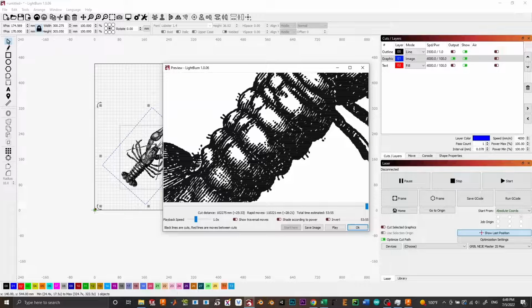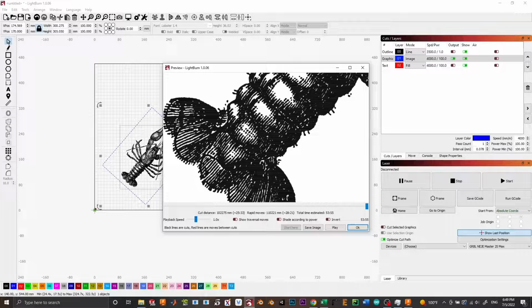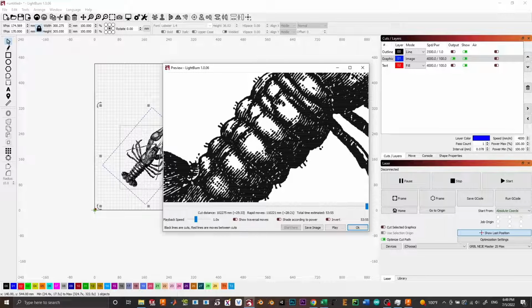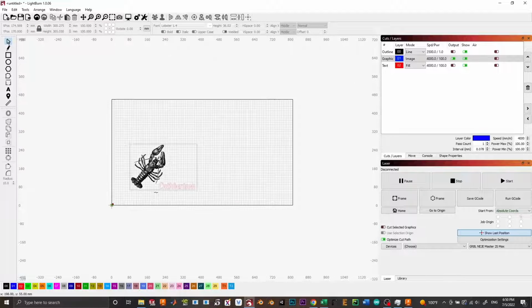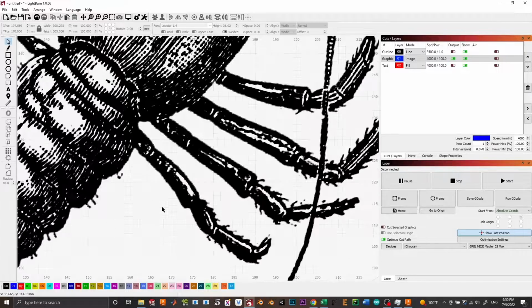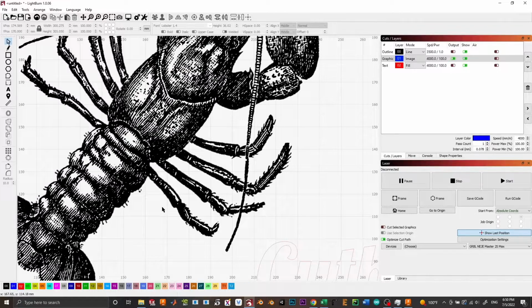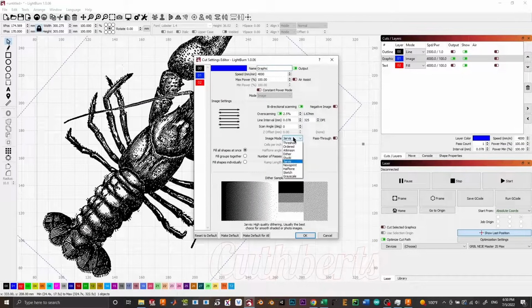One thing I do recommend, especially if you're making slate coasters, now working with slate charcuterie boards, is use some of your old scrapped coasters and just crop out a tiny section of this, about like so. Keep it scaled properly and have it engraved on a coaster just to see what exactly you're looking at, in terms of resolution, engraved time, stuff like that. It can be extremely helpful, especially for more photo-like images rather than graphics that will require dithering. Since this is just a straight black and white graphic, it doesn't require any dithering. If we were to dither it, then I highly recommend the Jarvis dithering. Especially for photos, it ends up with a really nice end result. But that's a different video.